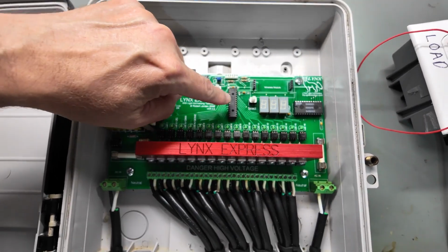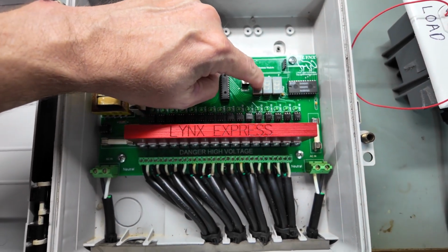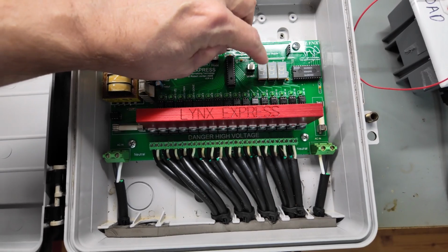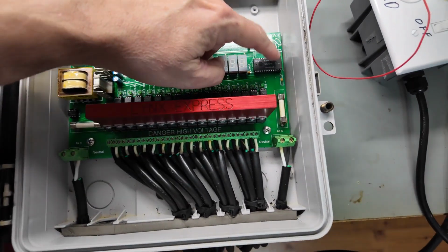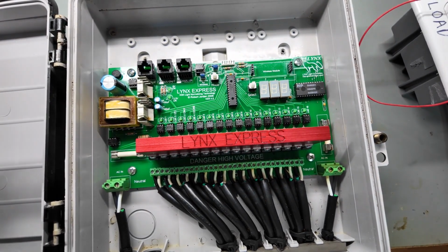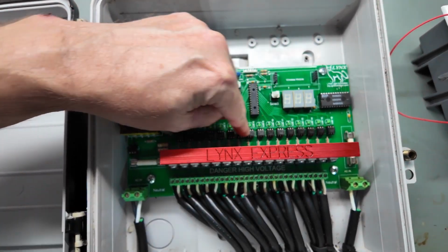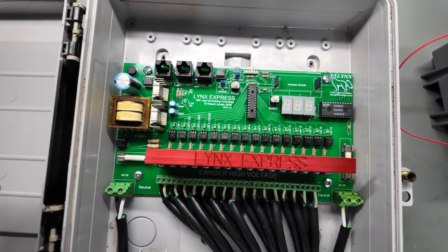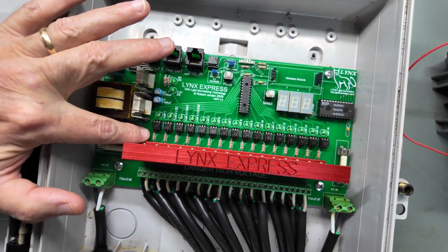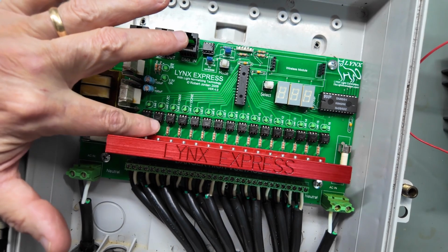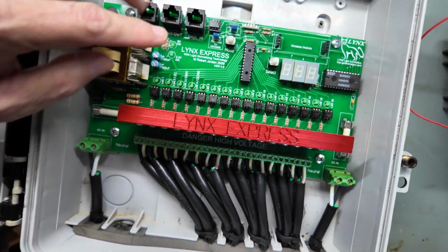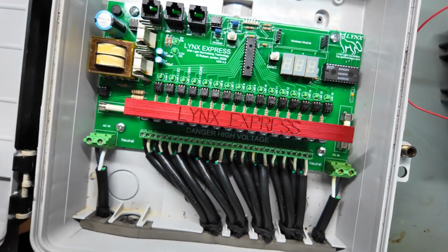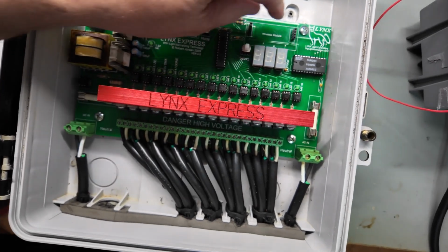And on this side you can see the PIC microcontroller, the LED displays, and the 2 push buttons that did all of the programming. This is an LED driver. These are optocouplers, one for each channel. Each one of these optocouplers drives one of the Triacs through this resistor. Each channel has an optocoupler, a resistor, and a paired LED. We have enough drive out of this chip not only to drive the optocoupler, but even to drive an LED for indication. You've got a place up here to plug in a wireless module.